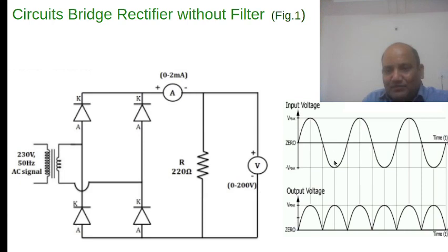Previously it was bipolar, with a positive half cycle and a negative half cycle, but here for the whole cycle you are getting only positive voltage. The negative pulse is converted. Why is this? Because the current is entering from the same direction. This is the direction of entering of the current, and because of that it is positive, and you are getting the cycle in the same direction.